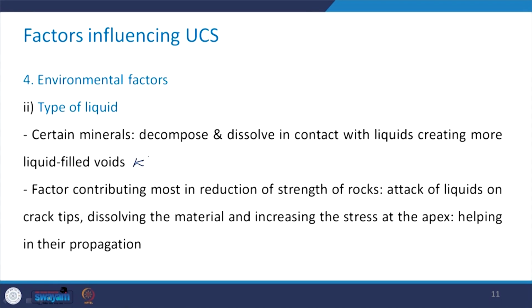Now, what happens because of the liquid? When this liquid comes in contact with the rock, there are always some cracks present in the rock. The liquid attacks the crack tip, and depending upon the mineralogical composition of that rock, whatever mineral is present at the tip of the crack gets dissolved in the presence of that liquid, and that increases the stress at the apex.